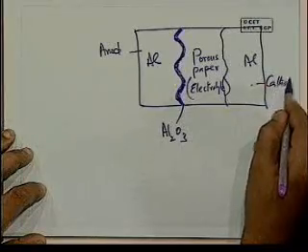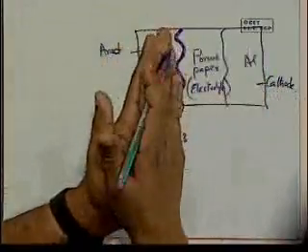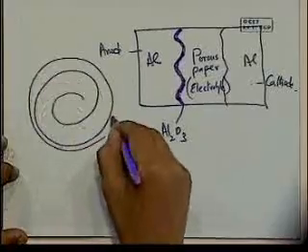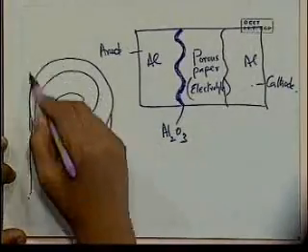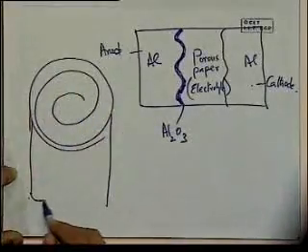Much like the polymer film, this is also created into a Swiss roll. Now here I don't need end contacts because the aluminum anode and cathode on either side serve as the end contacts. But these two things that are rolled together can be rolled up to create a structure like that. The whole thing is then enclosed in a case.